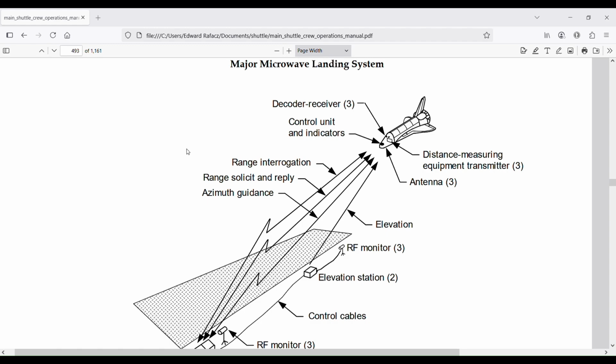is, if we go back to the cockpit and go to the HSI, the attitude ball, it's going to be here. This is the glide slope here, up and down. As we stated before, if you're close, it is 1,000 feet up or down that you are from the glide slope, and then 2.5 degrees either side of the runway. So these pointers are going to move and tell you where to go.